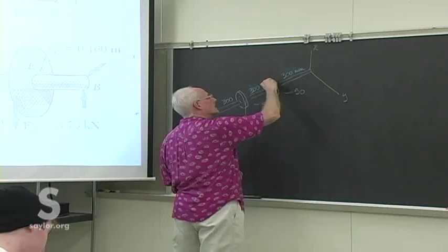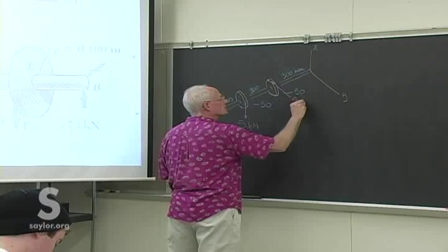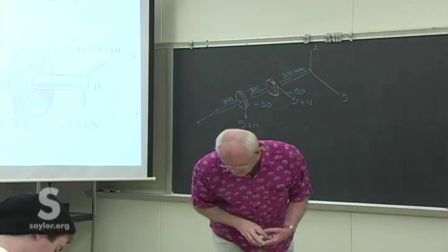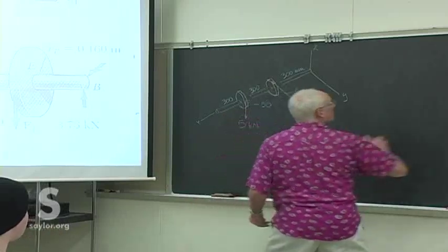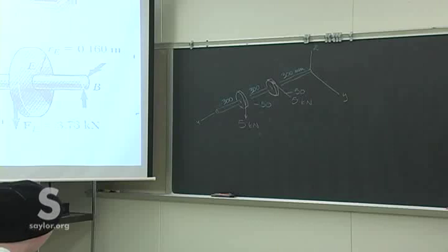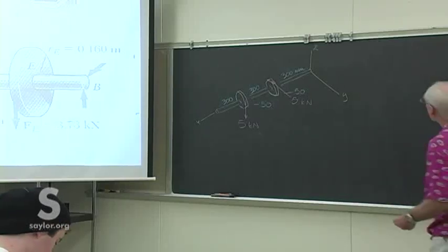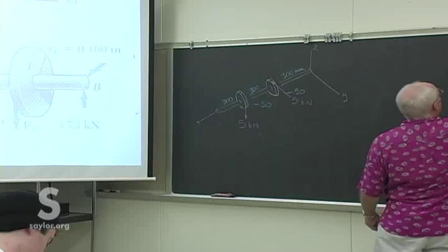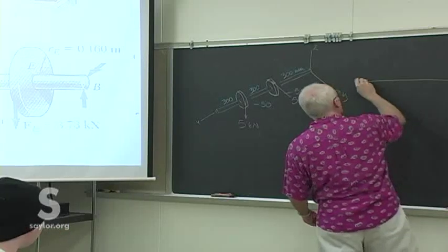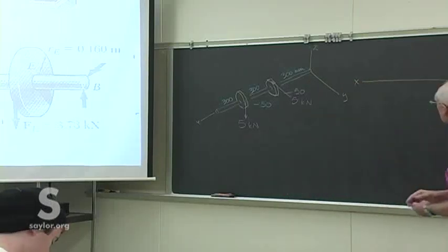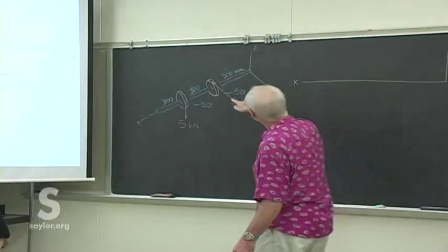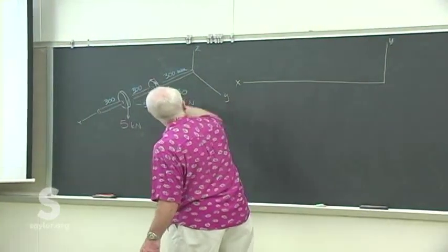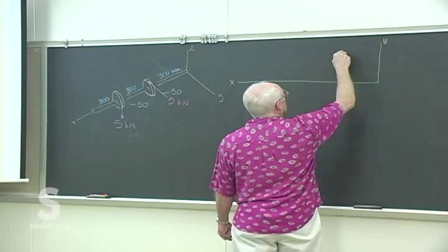Okay, there we go. So now we've got that force going in there, also 5 kilonewtons. Doesn't matter. It's a lot easier than if you take these in the side perspective. So we can do that together if that would help. So in the XY direction, remember, turn this force into a force and a moment, but we have a minus Y direction force of 5 kilonewtons.